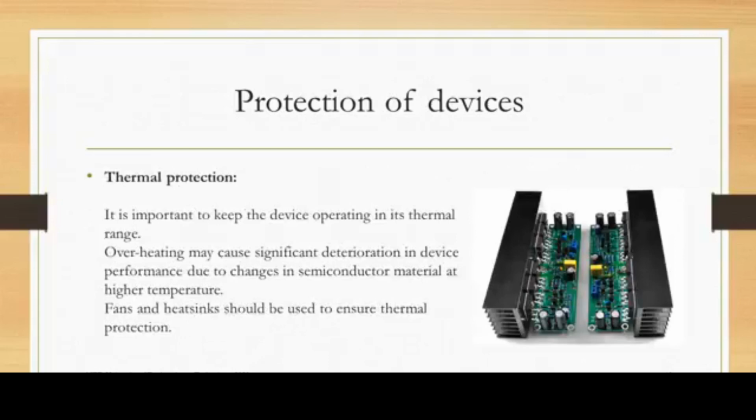And the third protection is against heat. Due to the switching losses and the on state of the device, heat is normally generated within the power devices. This heat must be transferred from the device to a cooling medium to maintain the operating junction temperature within the specified range. Although this heat transfer can be accomplished by conduction, convection or radiation, natural or forced air convection cooling is commonly used in industrial applications.